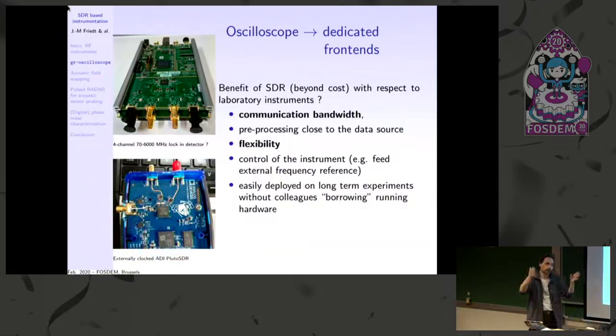Below that, it starts working at 10 megahertz, but between 10 and 40 megahertz you have very poor or degraded phase noise, so you cannot just take the hydrogen maser. You need to trick the synthesis a little bit: you feed it with your 40 megahertz input, and then you can do some sort of feedback loop on your control. So this is the kind of thing that software-defined radio allows you to do.